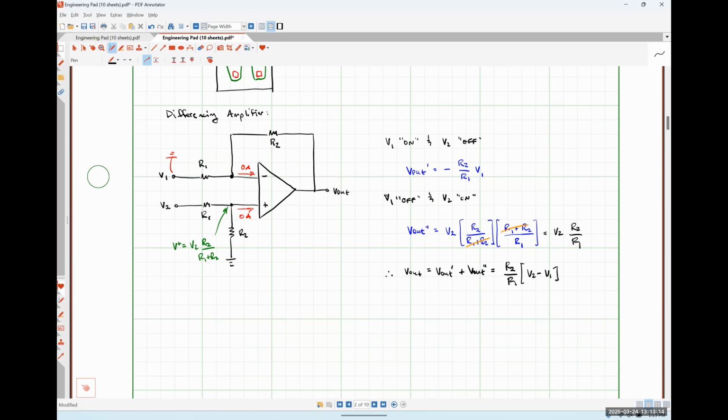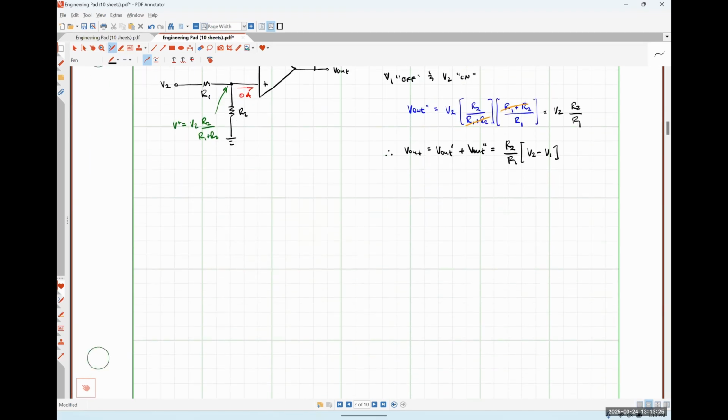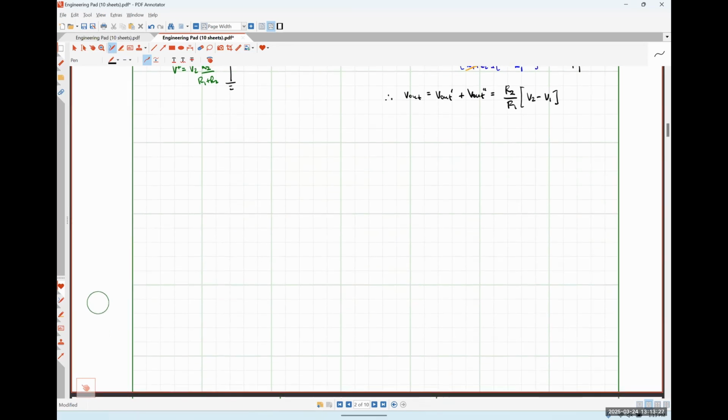So we've scaled our input signals. We've added input signals together. We've taken the difference of input signals. So now let's do calculus with op amps. Okay. So as a quick reminder over here on the right, I'm going to choose to implement these circuits using capacitors and resistors. We could implement these circuits using inductors and resistors.